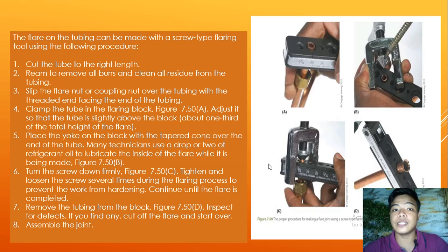There might be turbulence as the process goes. Next, slip the flare nut or coupling nut over the tubing with the threaded end facing the end of the tubing.